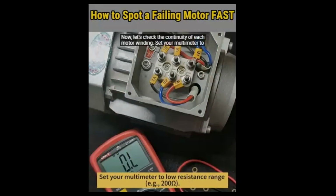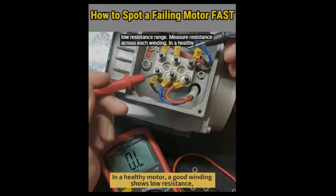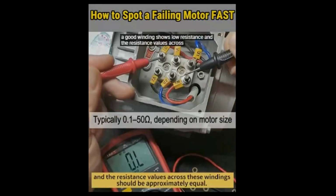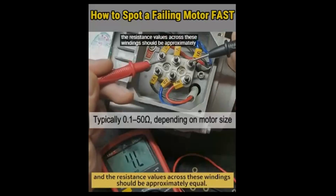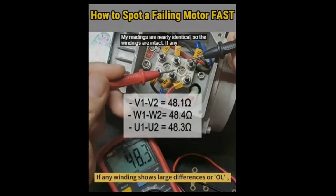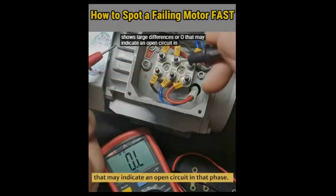Set your multimeter to low resistance range. Measure resistance across each winding. In a healthy motor, a good winding shows low resistance, and the resistance values across these windings should be approximately equal. My readings are nearly identical, so the windings are intact. If any winding shows large differences or OL, that may indicate an open circuit in that phase.